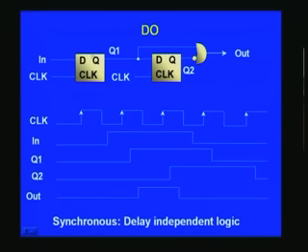The first flip flop output is Q1, and naturally when the rising edge clock is encountered at this point of time, in is 0. So naturally the output is 0 here, and subsequently it is 1 here, but this will be registered only at the positive edge of the clock.